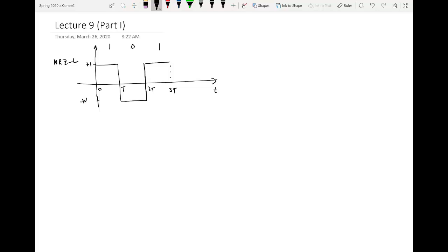These kinds of rectangular pulses are not physically realizable to transmit. If you transmit such pulses, because the channel is band limited, the pulses now become like this. For 1 it can be like this, for -1 it may be like this.